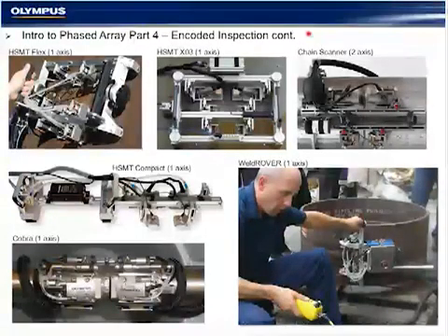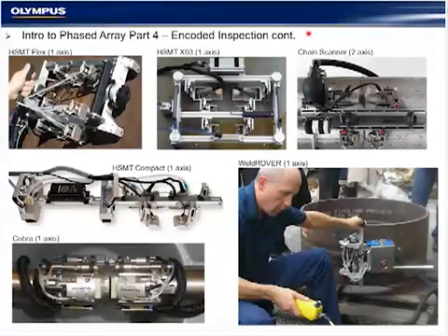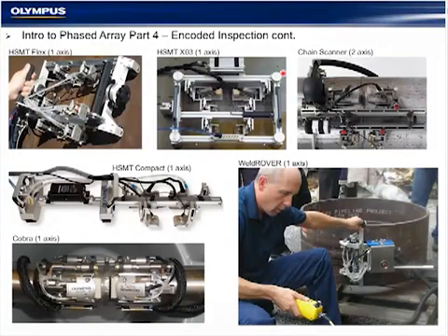All of the scanners can be repositioned, reconfigured. The probes can be moved in several different positions and orientations. Some allow the wheels to be rotated, like the MX2, for parallel scanning alongside the weld.